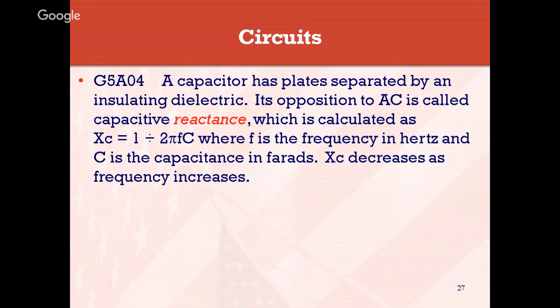And if the capacitance is in microfarads or picofarads or even nanofarads, you need to convert that to farads in order to work this formula. And remember, while inductive reactance increases as frequency increases, capacitive reactance actually decreases as frequency increases.